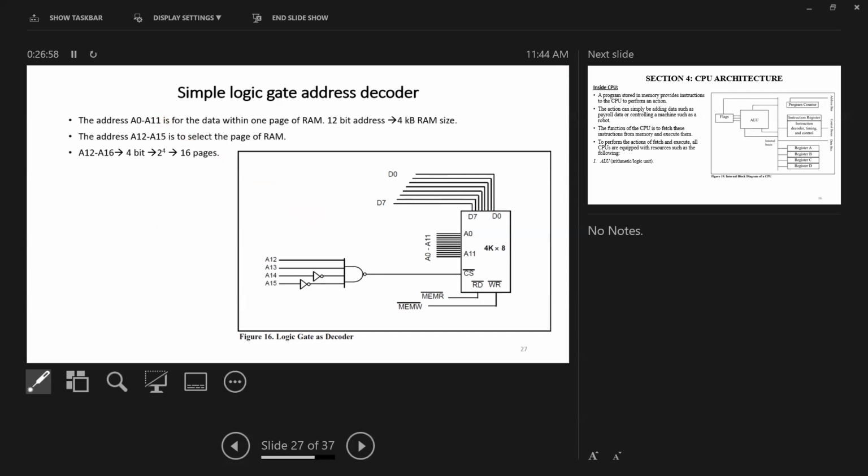We can draw the second one here. So we can have another page here, up to n pages. And all of this data would be going in parallel, and so on, up till the last data. So this is the data in parallel with all of the ICs. And then the address bus would also be connected in parallel with all of the pages.